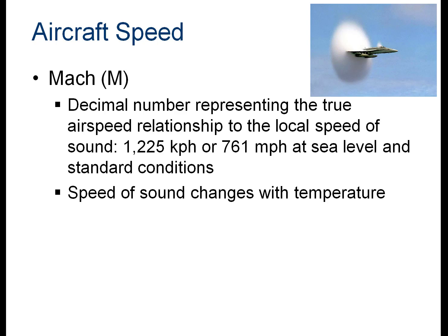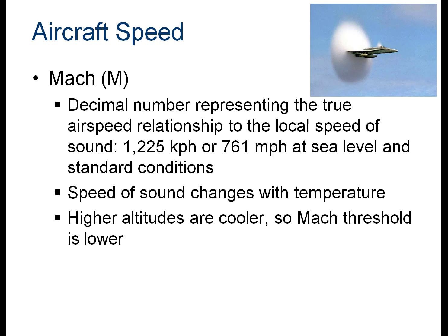Now the speed of sound changes with the temperature, and as I go higher and higher, it gets colder and colder. The speed of sound decreases as it gets colder. So the Mach threshold is lower also, but still going Mach 1 at 25,000 feet means I'm going the speed of sound at the temperature that's at 25,000 feet.